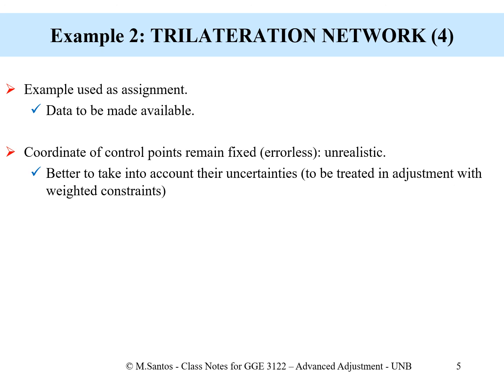Before ending, I would like to make a very important comment. In this example, we are treating the coordinates of the control points as errorless. We are disregarding their uncertainties; we're basically ignoring their standard deviations. This is not the best approach. It is common in surveying, I have to tell you, but it is not the best approach. I will call it unrealistic.